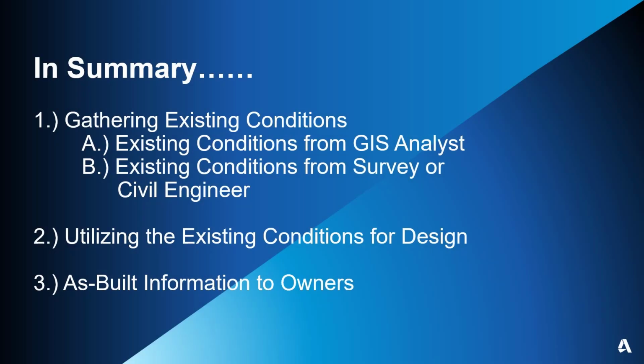In summary, when looking through the lens of the day in the life of a civil engineer, gathering existing conditions is always the first step in all projects. We were able to combine the surface information from the point cloud data, capture linear features from the point cloud in Infraworks, and then publish that data to ArcGIS Online for other use on existing or future projects.